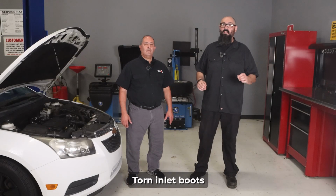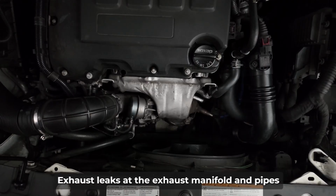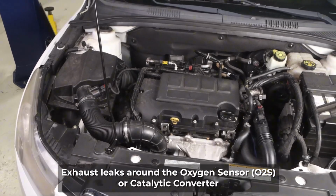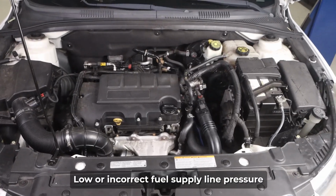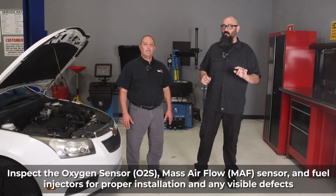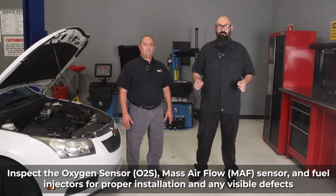Now, after gathering that information, perform an initial inspection for any obvious mechanical issues such as torn inlet boots, missing or broken vacuum tubes, exhaust leaks at the exhaust manifold and pipes, exhaust leaks around the oxygen sensor or catalytic converter. You also want to check for low or incorrect fuel supply, possible vacuum leaks, and inspect the oxygen sensor, mass airflow sensor, or any obvious visible defects. Next, refer to the service manual or any applicable TSB for any additional diagnostic information before you continue. Now that that's done, we can go ahead and scan for codes and continue the investigation.